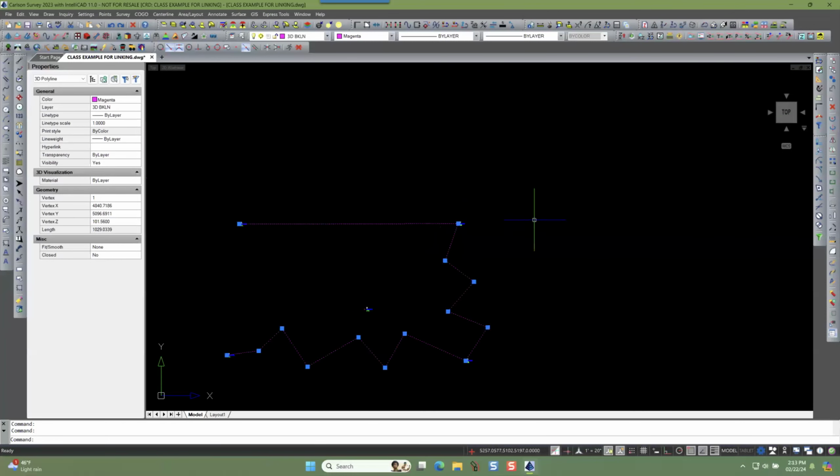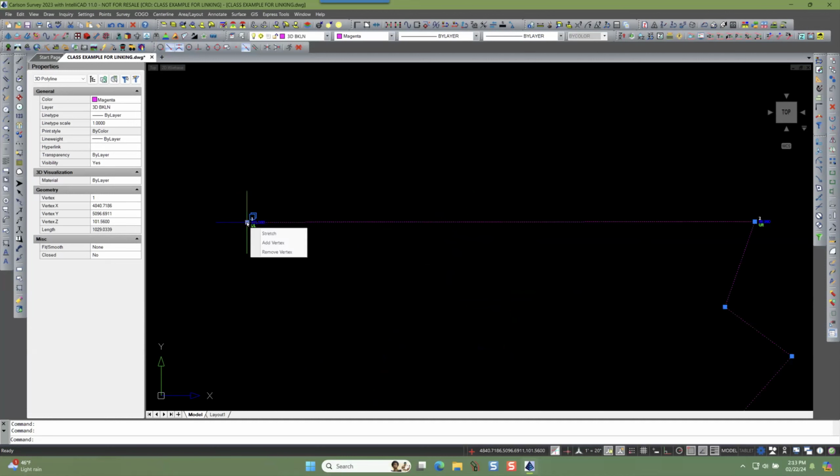And therefore, so are all of these ones in between because it interpolated it, but they're the same elevation. All right, so that gave us that. This one is 101.56. Now I'm reading that down here on the bottom of the screen on the status bar when I hover the mouse. There's my 101.56, and that's what that elevation is.